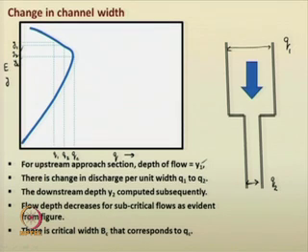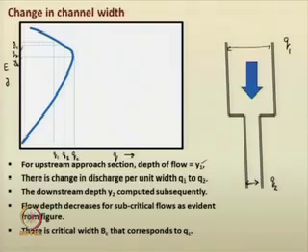So, you can see that for any quantity q, the maximum discharge per unit width occurs when it is in critical condition for the rectangular channels. From this particular curve, it is quite obvious. So, you cannot have a discharge beyond the critical conditions in that channel, right. You cannot have more than that quantity. This is the maximum possible and the corresponding depth is that much.